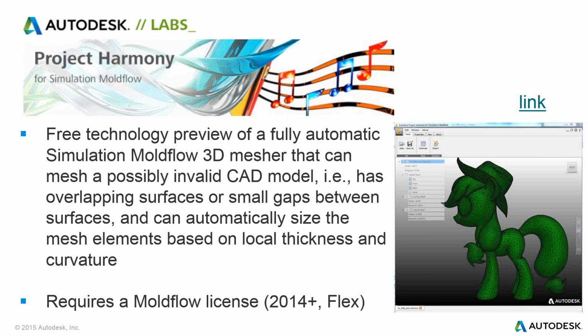So in this case, areas that are flattish will have a mesh size that's significantly coarser, because they can be coarser there, and areas that are very detailed, or have a big transition in thickness, for instance, or features associated with it, we will refine the element size in that area automatically.